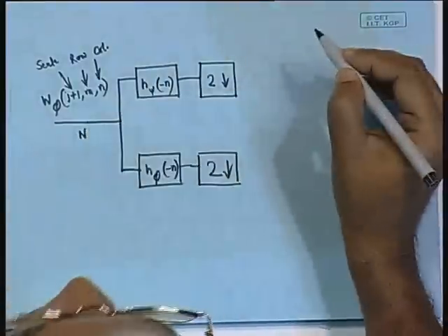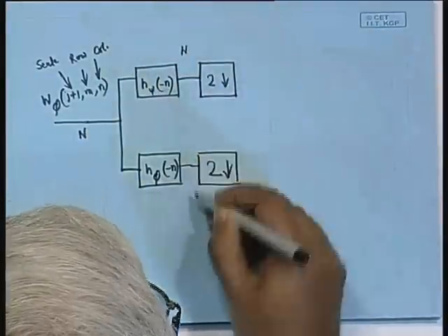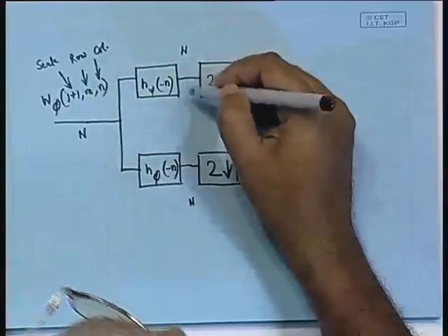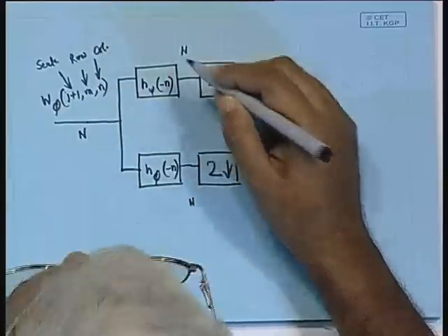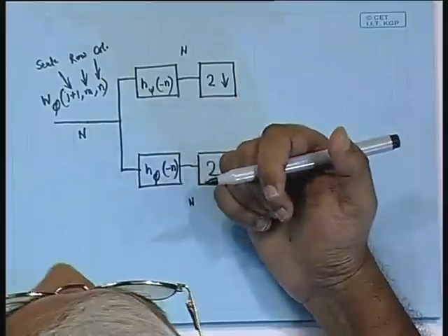So, which means to say that if we start with n number of samples over here, then at the output of each of these filters we will have n samples at the low pass filtered as well as the high pass filter, but individually their bandwidth is halved. Okay. So, out of these n samples only n by 2 samples will be required for both the low pass filtered and the high pass filtered version.